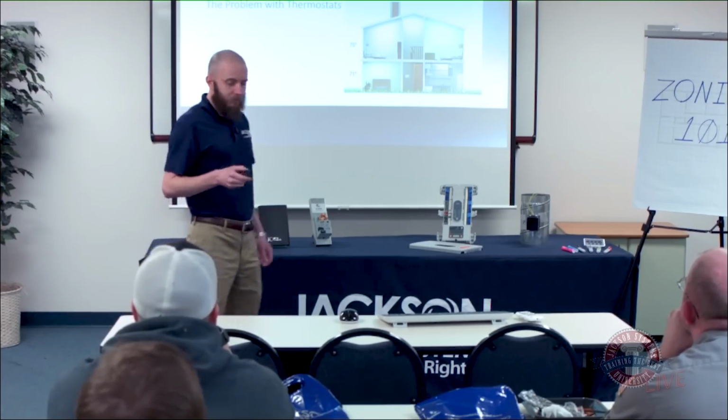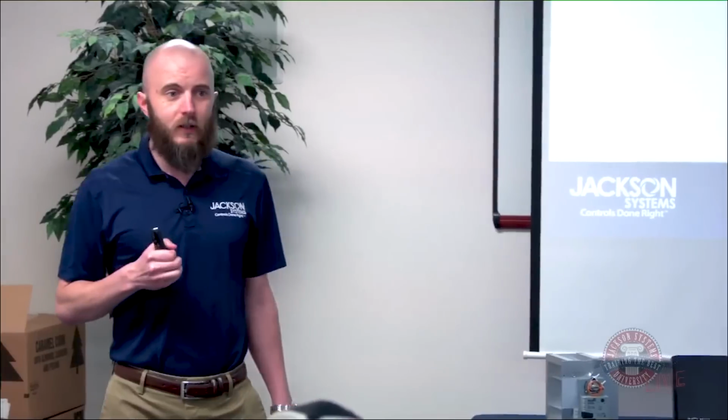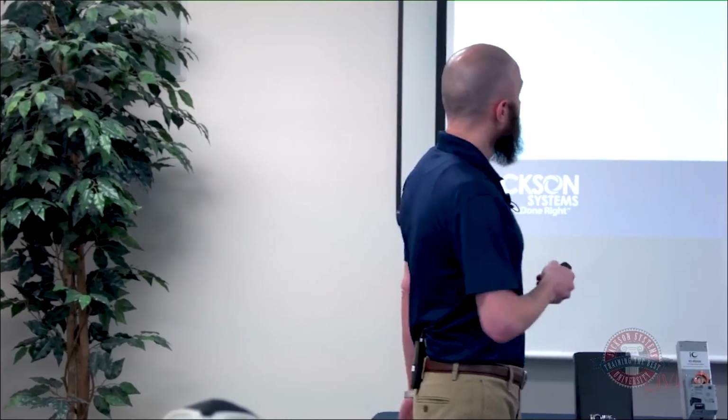So you're frequently going to see stuff like you see on the screen now where you got a two-story house and it'll be nice and comfortable downstairs in the hallway where the thermostat probably is, and upstairs it'll be a few degrees warmer, and on one side of the house it may be warmer where the sun's shining and all that, and that's just natural, the natural sources of different loads.